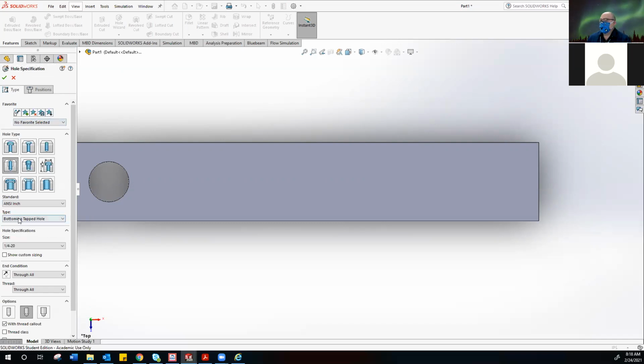All right. Let's do our size. Everything's about the same. We just need to change the size on this because it's still going to be a through hole. The through hole size that we're looking for is a 10-24. So we're going to have to scroll up. It's going to be hashtag 10-24. That's what we're looking for. It's a little teeny tiny machine screw. So go ahead and click on 1024. Everything's good. It's a through hole, it's threaded, in theory.